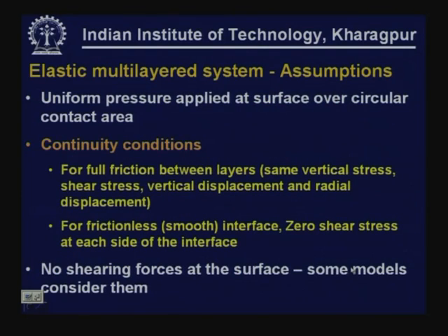Other assumptions that we make about the loading conditions and boundary conditions are: uniform pressure is applied at the surface over a circular contact area, although we can still solve the pavements for other types of surface loading conditions. The continuity conditions are: between different layers, full friction is assumed, that means same vertical stress, same shear stress, same vertical displacement and same radial displacement at the interface.